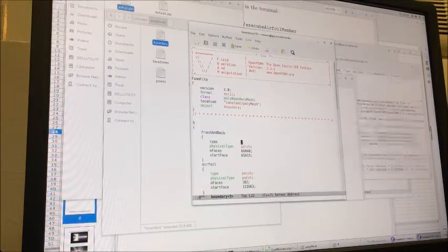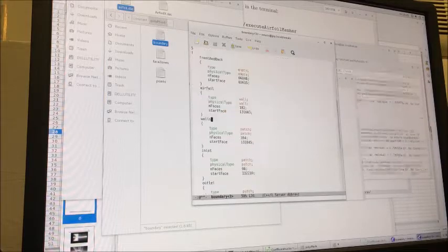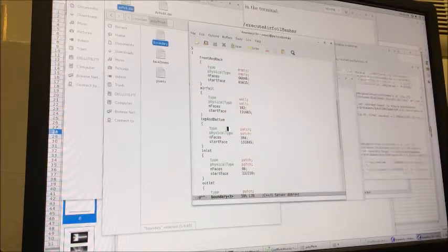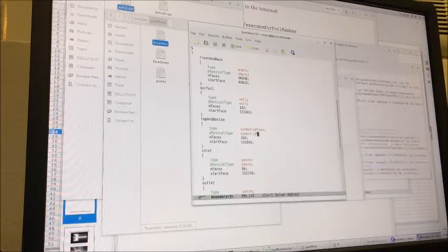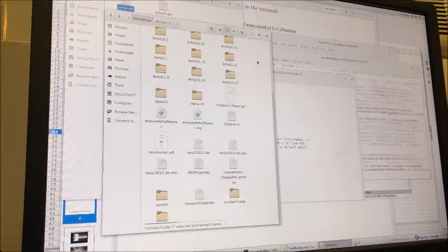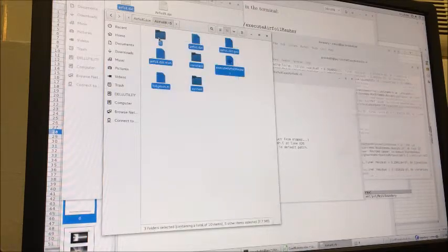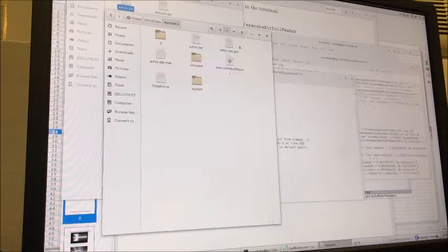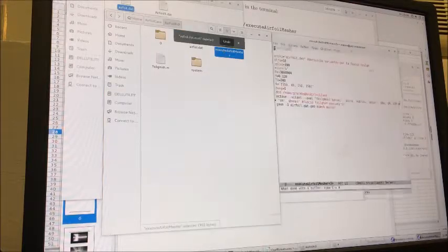My main job is calculating the lift coefficient, drag coefficient, and pitching moment of each of these 11 airfoils at different angles of attack. We calculate this data primarily using a program called OpenFOAM. At its core, OpenFOAM is a C++ library that can be used for a variety of calculations dealing with pre-processing, solving, and post-processing. Here I'm running a simulation in the background to find those coefficients for a certain airfoil at a certain angle of attack.